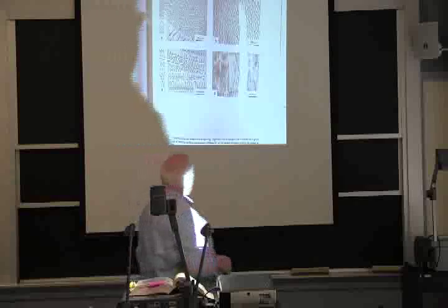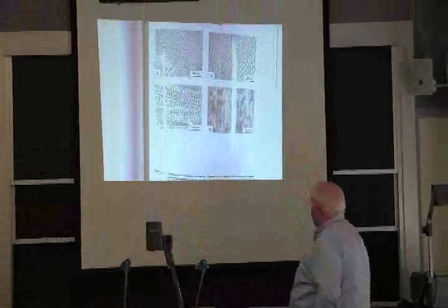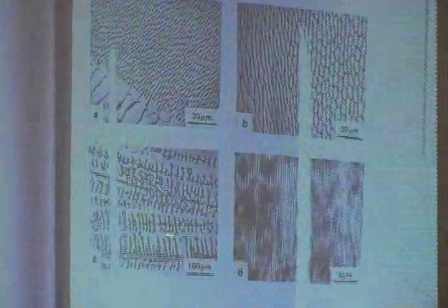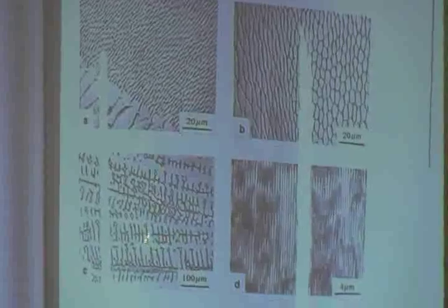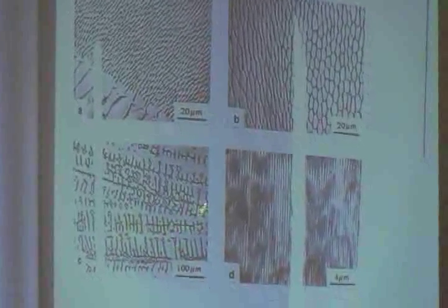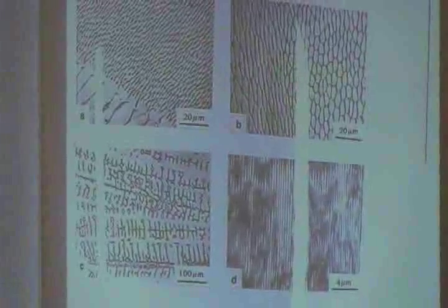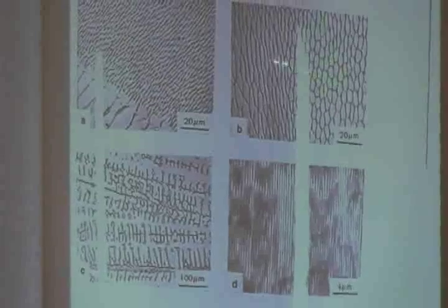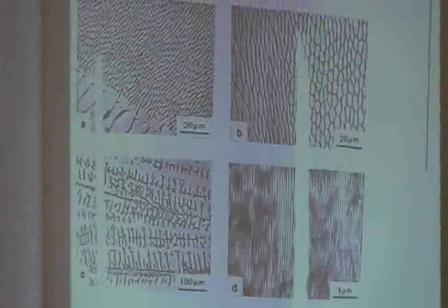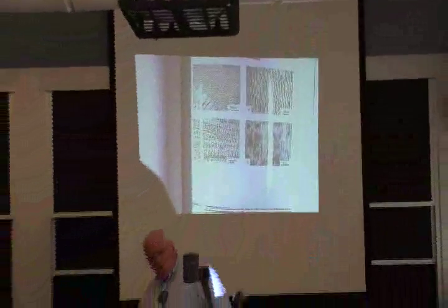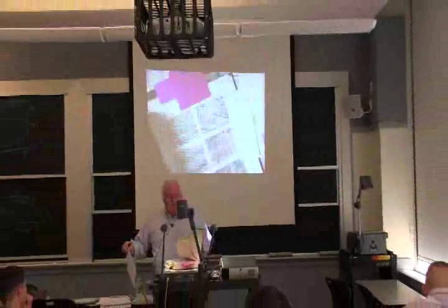Instead of just dendritic structures, this is a similar dendritic structure. Dendrite comes from the Greek word that means trees, and this is sort of, if you turn it sideways, a tree with branches. And you can also get cellular structure, where you have cells, and the black outline, these are individual fingers of material that are growing as the heat's extracted.